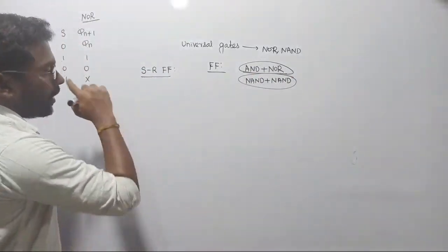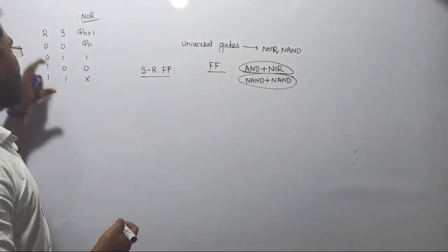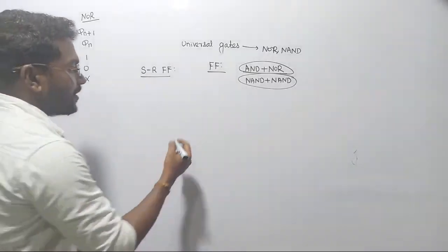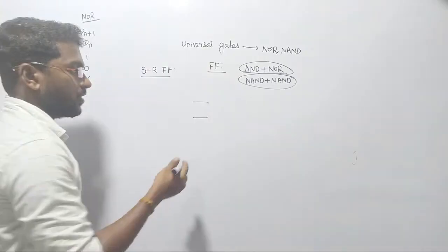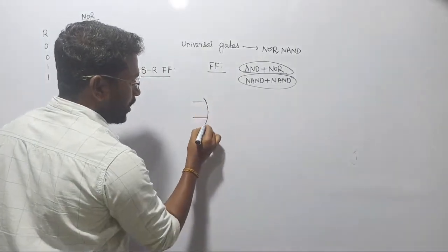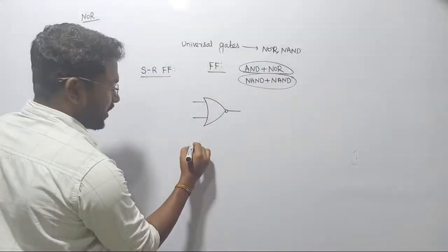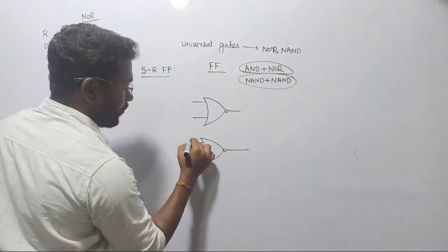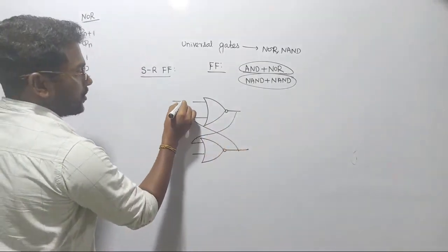Anyway, I would like to design this SR flip-flop with the help of the NOR gate. Already we have the NOR latches truth table here. So let me take the latches first and let me show you how we are bringing the modified version. Let me close these 2 circuits first. Once again we are considering latches only. First we will consider latches, and then we will modify the circuit. This is cross coupled NOR gates, and there are 2 input lines.